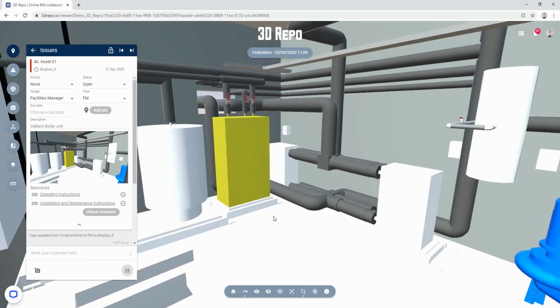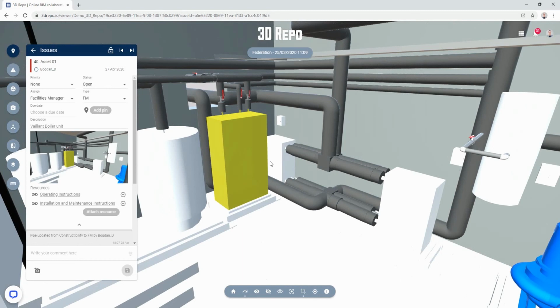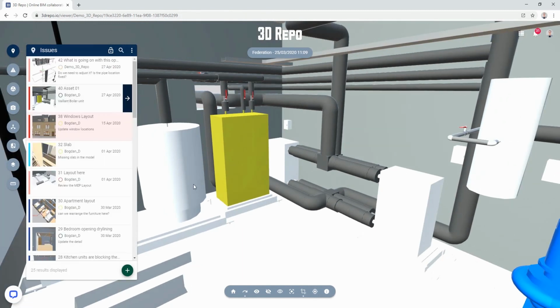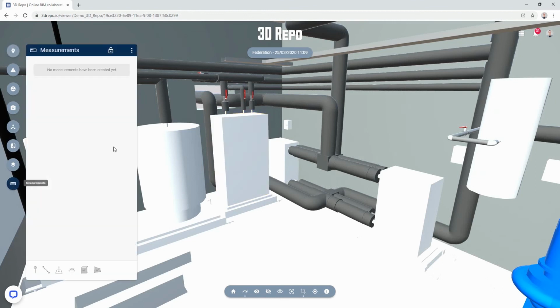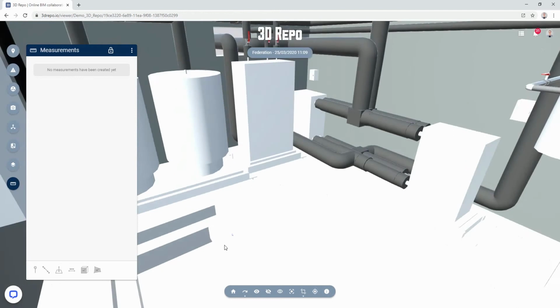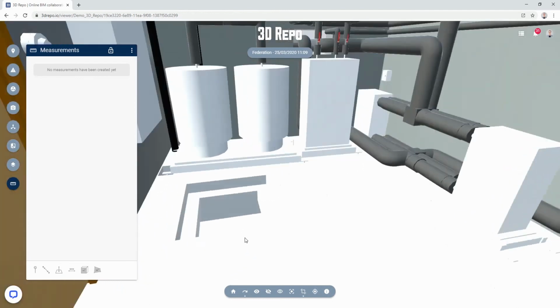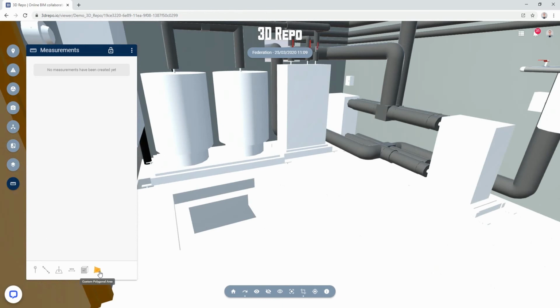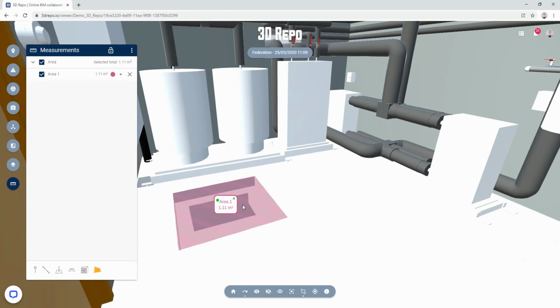And when you do this, you're not just limited to looking at things, right? For instance, if you're looking at this particular area and you say, okay, I want to validate a few things in here as well, you can jump to other tools such as the measurement card. If you start noticing that there is some sort of slab opening in here, and I want to understand how big it is, you can drop a custom area if you want to. As simple as that. I snap onto the corners, I measure this opening.